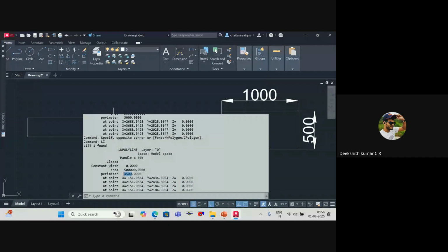That will result in lesser air volume because you're increasing the surface area. More volume of air will be going with lesser velocity because it will be touching that particular surface. You agree or not? For that reason, you have to avoid higher aspect ratios.